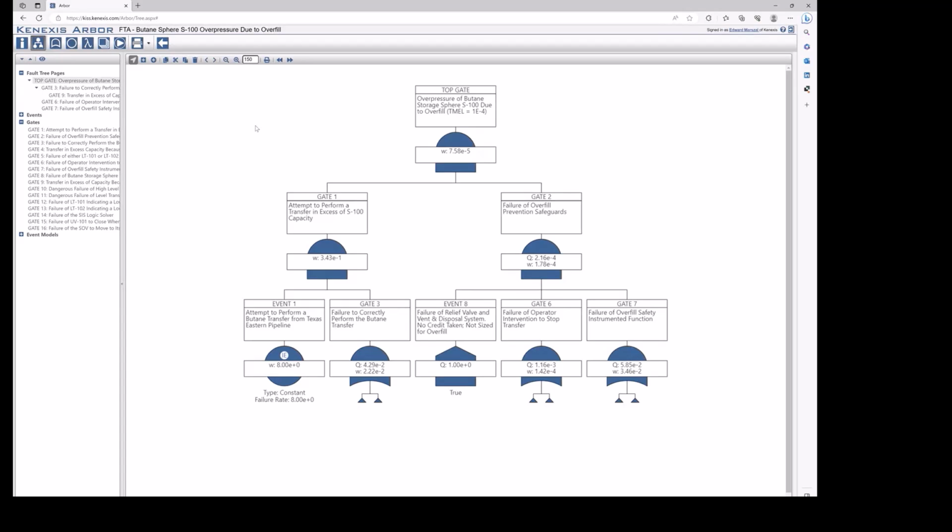And you don't need to go into the super detail of a fault tree unless it's a complex problem. But please put those templates together for your LOPAs and your HAZOPs of your very common scenarios, like fired heaters, heat exchangers, reactors that you run into a lot. Templating, underutilized, extremely valuable tool.